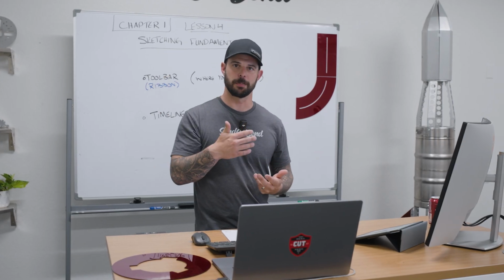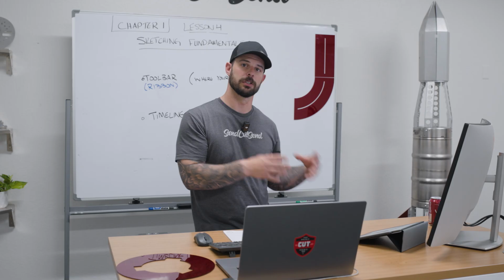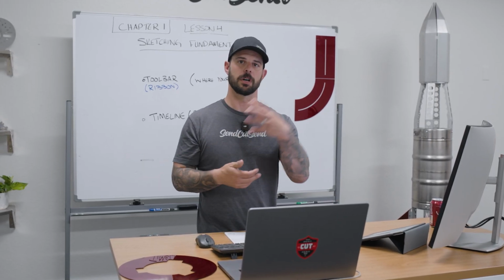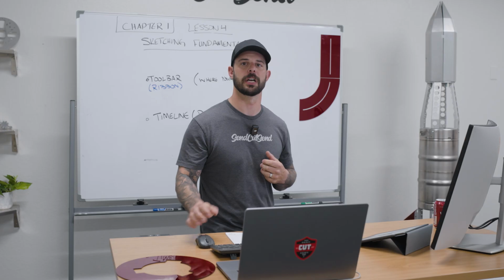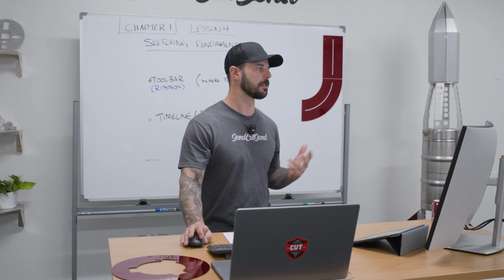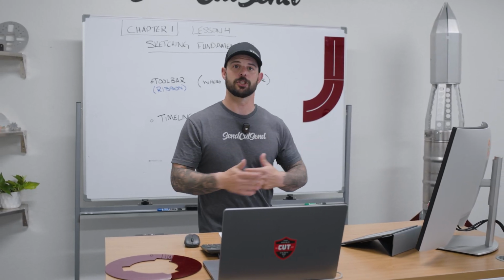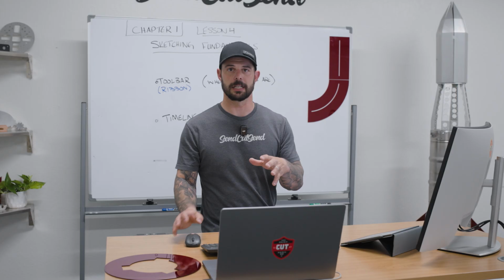When you finish your sketch, that tab disappears and the sketch is now logged within your history, but you don't have that palette anymore. You don't have the tools showing up anymore, and people get very confused about it. The way you get it back is just reopen your sketch. Go ahead and click edit.